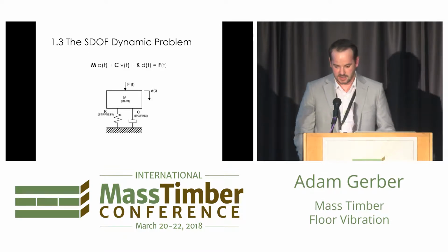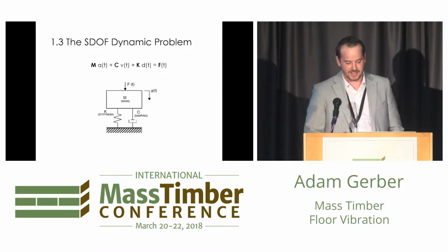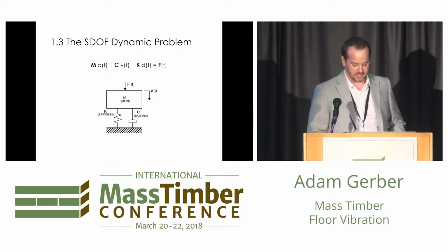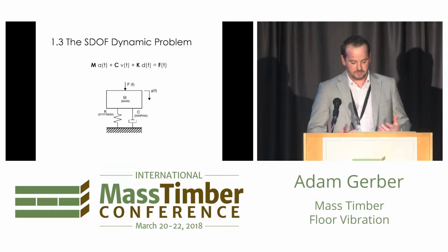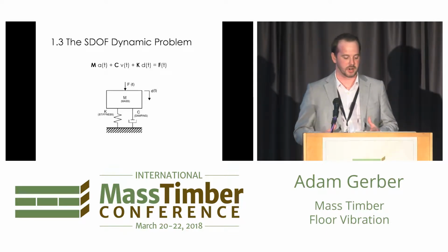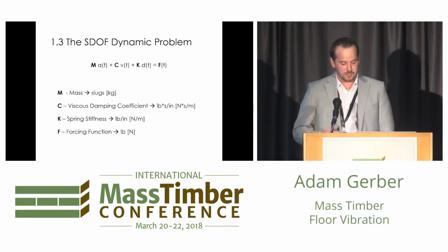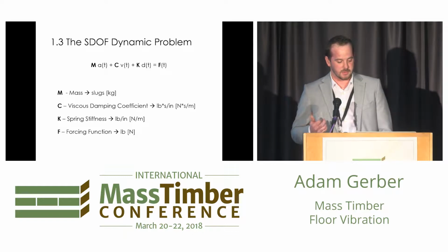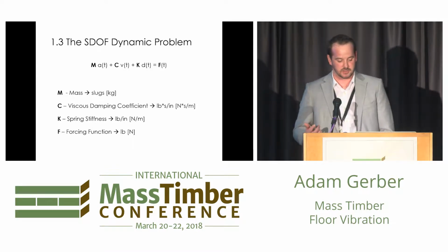I promise I'm going to burn through this really fast, but there is a little bit of math just to paint the picture so that we can talk the same language. The easiest dynamic problem to solve is a single degree of freedom problem, basically a mass and a spring. There's a mass term, a viscous damping coefficient, a spring stiffness, and a forcing function.